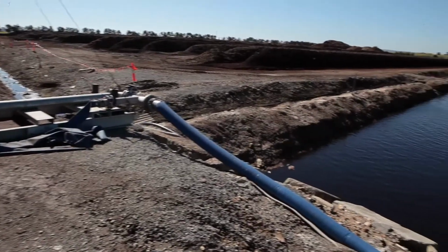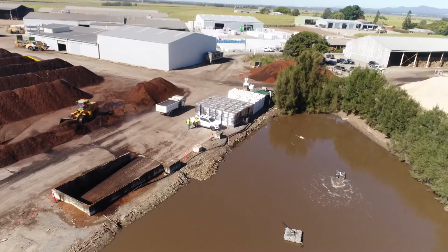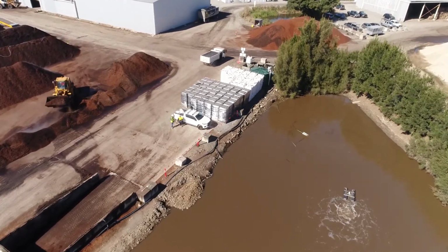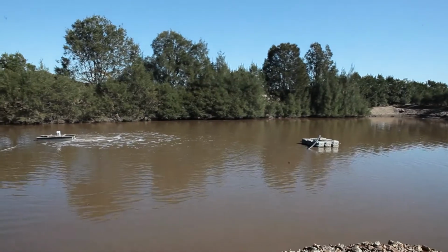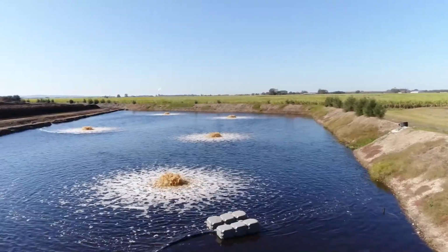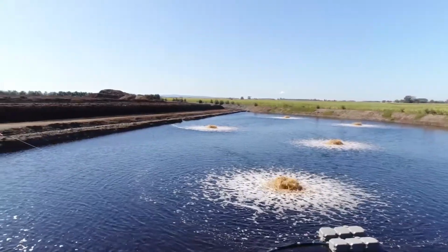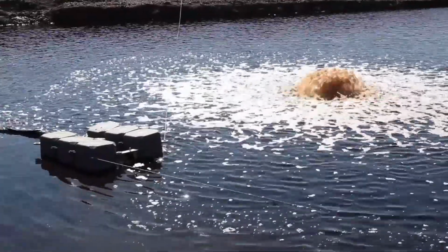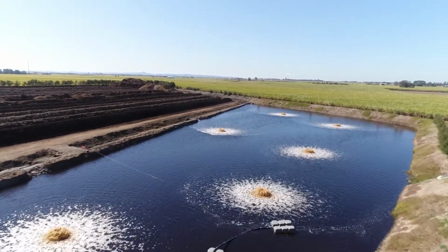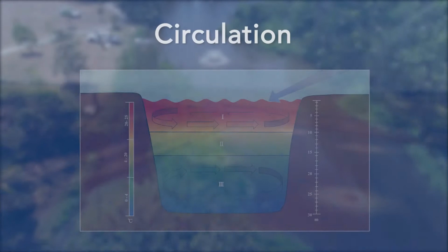Aeration device selection is generally determined when considering some key factors about the water body's usage. In wastewater dams, generally the more oxygen being transferred equates to improved results. Higher oxygen transfer rates are produced by subsurface aerators that produce a microbubble. This is not always applicable, particularly in wastewater environments where the bottom sludge accumulates large amounts of toxic metals and gases that can be released if the sediment is disturbed. In cases like this, it is more beneficial to apply surface aeration and minimise any significant disturbance of the bottom sediment.